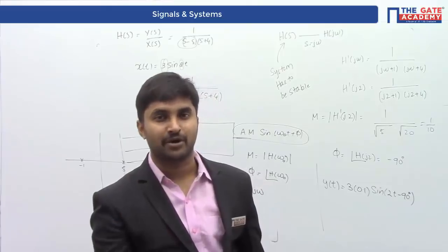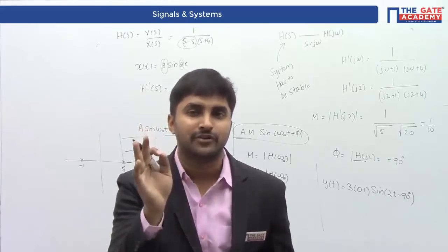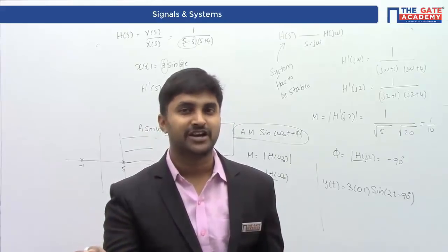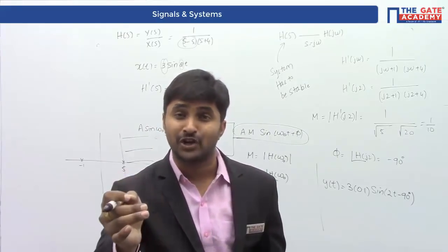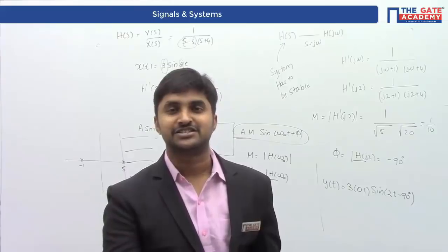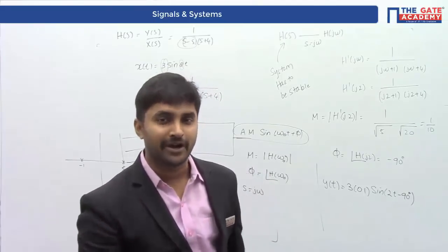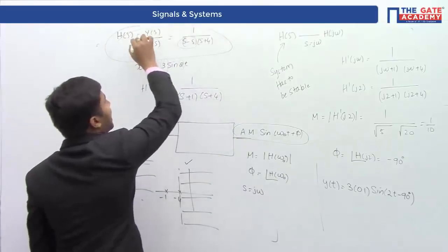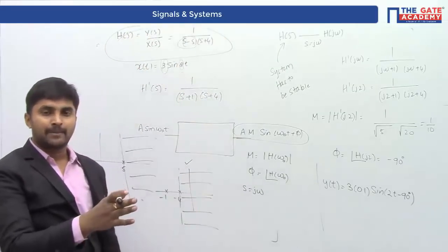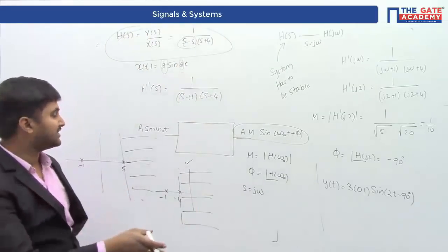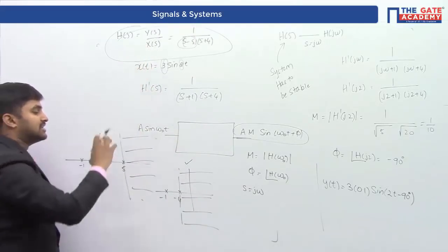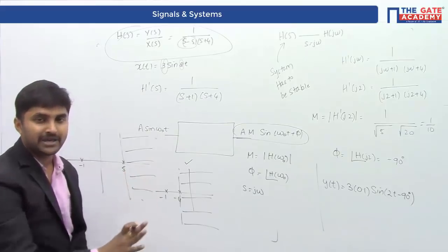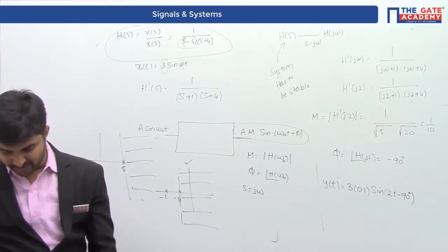Please, it's a very important point that whenever we want the Fourier transform from the Laplace transform, you should always ensure that the system is going to be stable. Here, when I have an actual transfer function, I will not apply the Laplace transform to Fourier transform, because if the system is considered to be causal, it cannot be stable. So I think we have covered the third part of it.